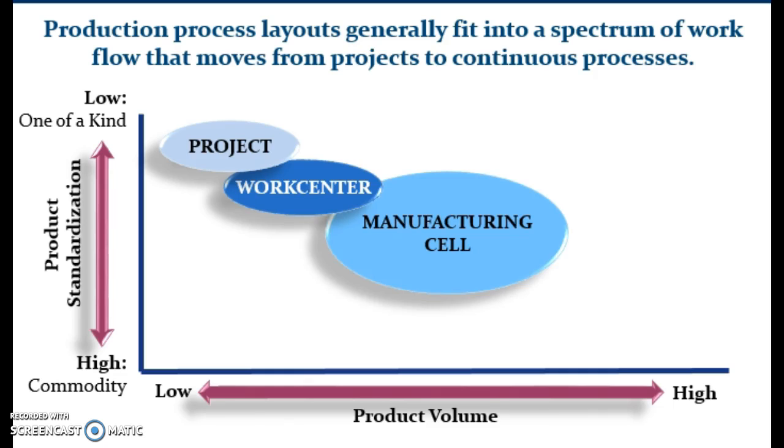The manufacturing cell is another process-focused layout that dedicates production areas to a narrow range of products that are similar in processing requirements. Setting up a manufacturing cell involves 4 activities: identifying families of parts with similar flow paths, grouping machines into cells based on part families, arranging cells so material movement is minimized, and last, locating large shared machines at the point of use.